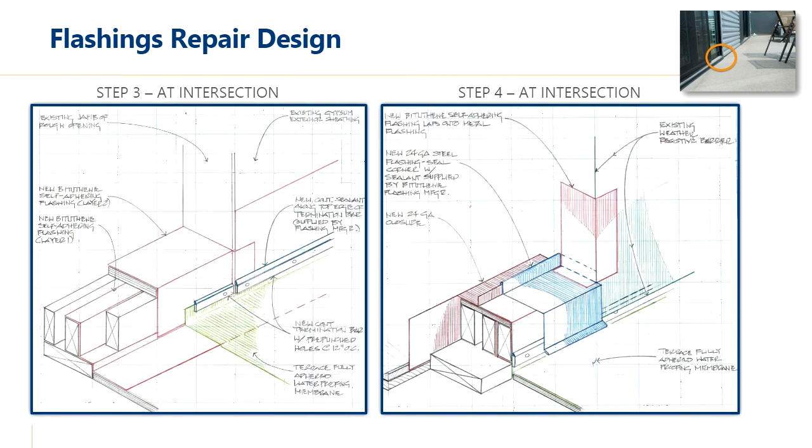We also wanted to show how those flashings would be terminated, integral with the balcony waterproofing or terrace waterproofing, and how they interacted with the jambs at the sliding glass doors. And this is one way to do it with this color-coded stepped isometric detail.